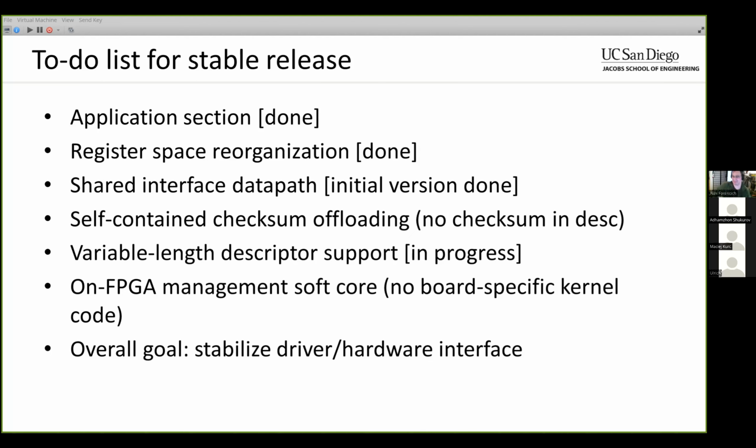But anyway, it sounds like there's something weird going on in the checksum computation, and if we fix that, maybe that will help. I mean, we should fix it, no matter what. But it sounds like that could be what's going on here. For me, my gut feeling is, does it really have something to do with the checksum calculation? What I'm thinking is, do we have a problem with descriptor fetching? Reading the wrong bit in the descriptor for whatever reason.